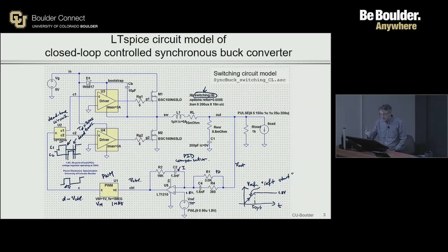All right, now we have C1 and C2. Those are still logic level control signals. We then pass them through gate drivers, and those are the gate drivers you have right here. You see we have two gate drivers, one for each MOSFET. The low side gate driver shares the same ground as the ground of the power MOSFET. The upper side gate driver does not.